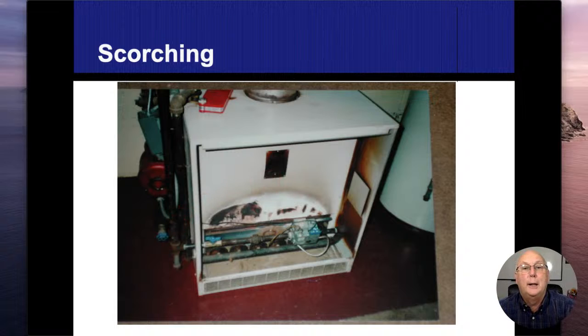Now this is on a hydronic boiler, and you can even see all the rust over here as well. So chances are we had a lot of flame rollout and it's coming up on the sides. It does bring with it a whole bunch of humidity. And it may have been fixed. We don't know. All we can do is identify what it is, give a probable cause, and then let somebody else come in here to do a diagnosis. Right.